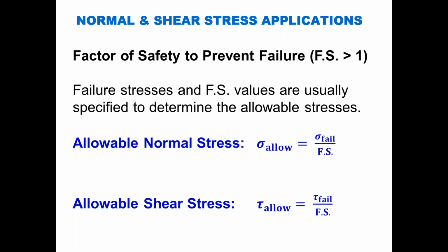And then we might actually make the factor of safety a larger value, just simply because if that particular component were to fail, there would be this catastrophic effect. In other words, it would be a really major failure. Maybe it would lead to loss of life or injury in the person using that or occupying that structure. And then maybe there's some other components that maybe if it were to fail, it would be a minor inconvenience, but it certainly wouldn't lead to anything major happening.